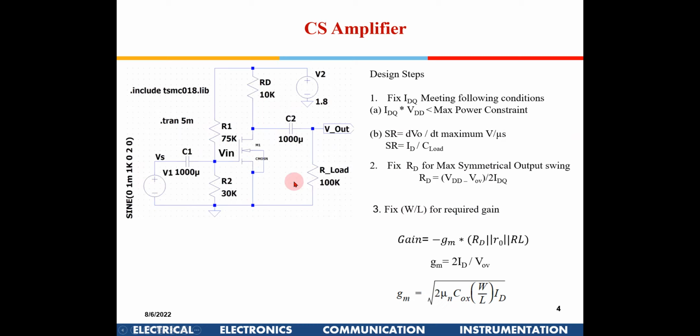Then we talked about in general how to do a hand calculation of finding out these resistances. I told we need to set this as VDD by 2. That is okay when the voltages are high, but as somebody brought out in the last class, if we are working at lower technology nodes and this voltage is around only 1 volt, we need to consider the overdrive voltage.